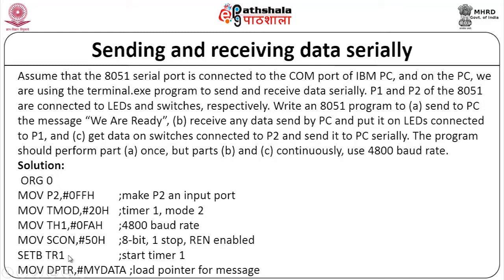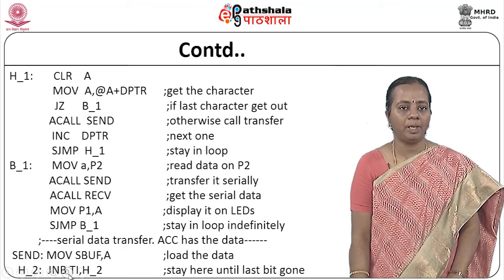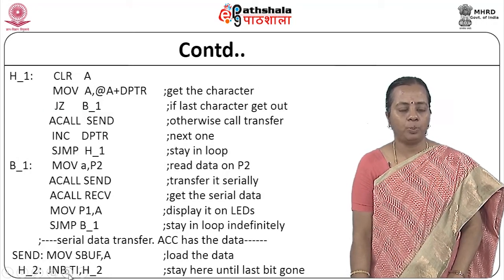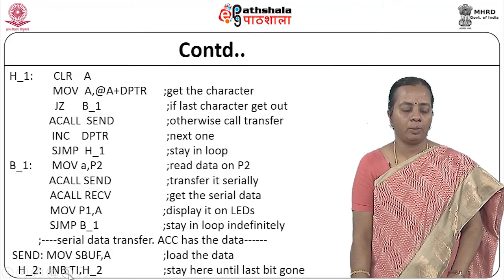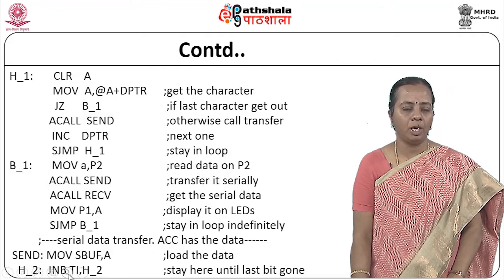So we start the timer by setting SETB TR1, and now I move the address where I have written the data to my DPTR. The DPTR, the pointer to the external memory, holds whatever address we want to point to in the external memory.